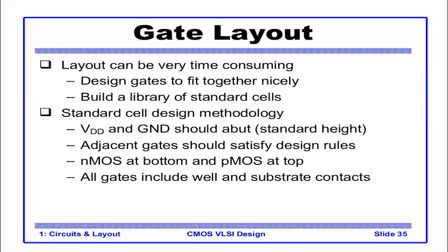So layouts, in fact, are very time consuming. The gates have to be fit together nicely. It's one thing to make a complex gate out of transistors, and it's another thing to lay them out. The actual area of the gate, how much space the gate occupies on silicon, is very much determined by how well it is laid out.